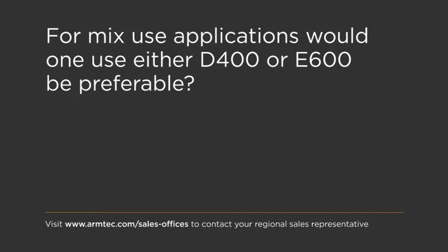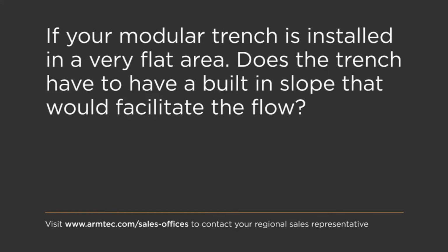Excellent. This is an interesting one. If your modular trench is installed in a very flat area, does the trench have to have a built-in slope that will facilitate flow? That's a really interesting question. Well, we have the hydraulic program that we use to choose the right system. But to answer the question quickly, no, it does not need to have a gradient, even if it's a level system, a level surface.